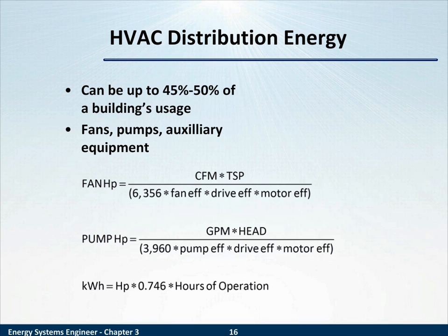You can do one of two things. You can reduce the temperature of that cold water and save energy if it's colder than it needs to be. Or you can reduce the flow of that cold water and it'll come out of that coil a little warmer. Balancing the flow and temperature of the water in your centralized system is where you find a tremendous energy saving benefit.